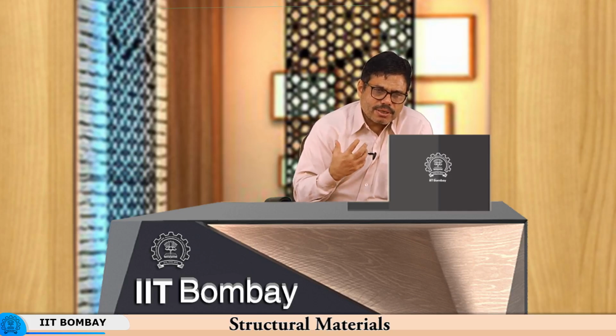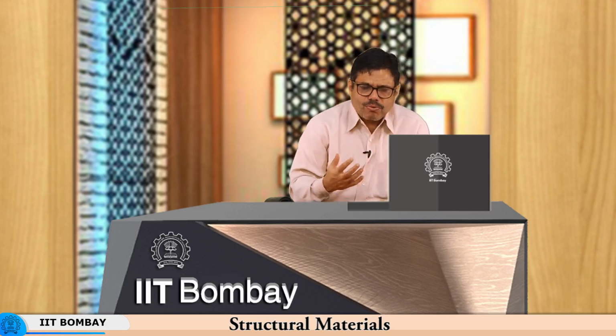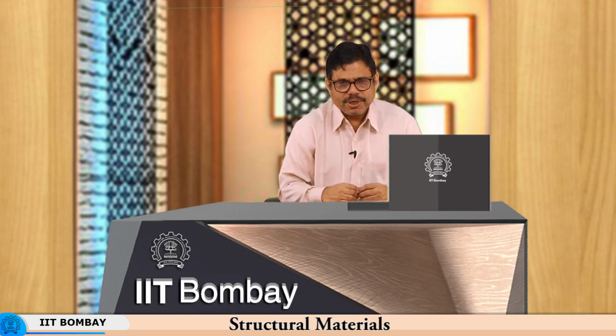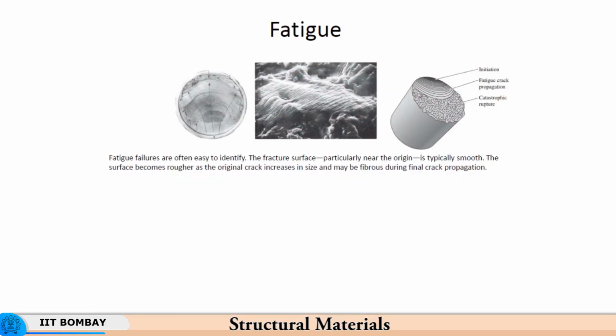So, the material has had the kind of fracture toughness which has resulted in arresting the crack. The crack has not propagated all at once, not in a catastrophic manner, but it has been arrested from one cycle to the next. So, the crack has been propagating very slowly from one cycle to the next. What it means is that when you are loading the workpiece, although things may not be visible from outside, the defect inside could be silently growing until the defect reaches such a size that there is a sudden failure or sudden fracture of the workpiece or of the component in question.